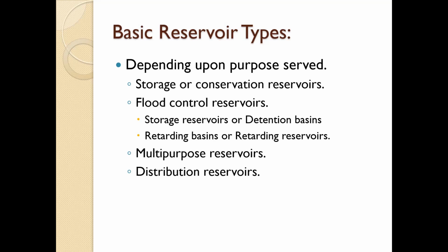In storage reservoirs, the flood crests downstream can be better controlled and regulated properly, so as not to cause their coincidence. This is the biggest advantage of such a reservoir and outweighs its disadvantages of being costly and involving the risk of human error in the installation and operation of gates.